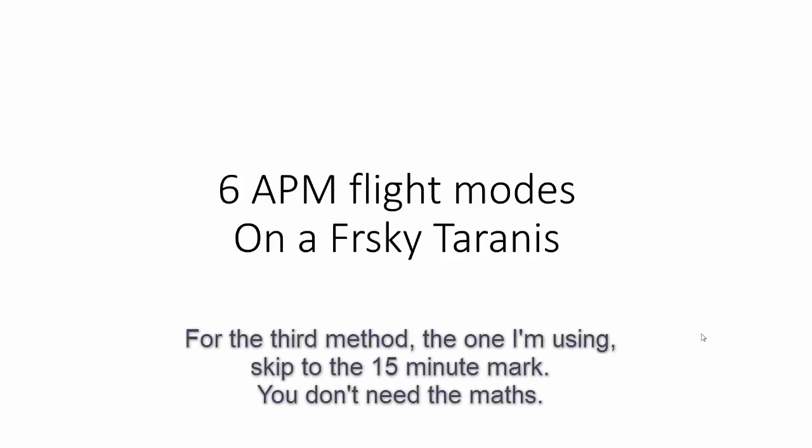Hello, I'm going to show you how to use all 6 APM flight modes on a Frsky Taranis. I'm going to go through 3 different ways of doing that, 2 with mixes and 1 using custom switches. The Taranis doesn't have a 6-position switch, so we're going to have to combine 2 switches.